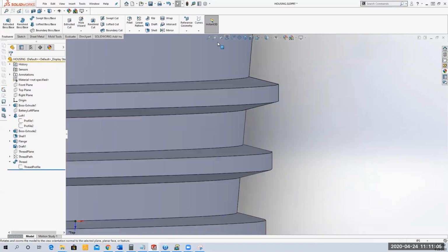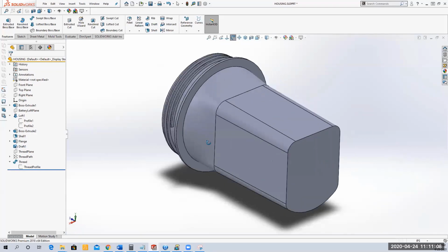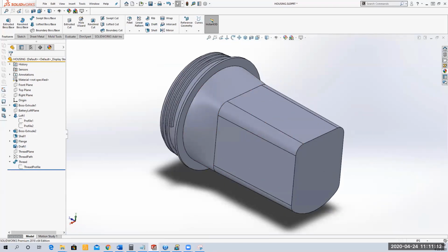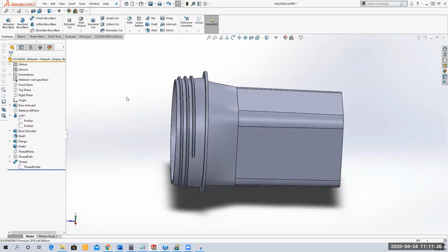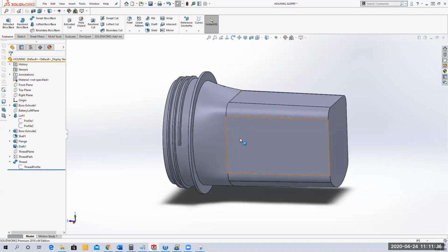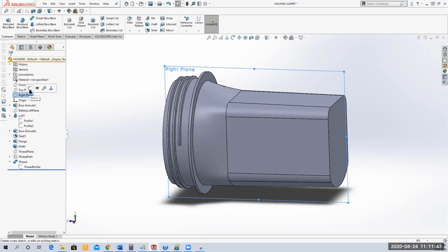Yes. Bravo. Okay, so now we are on the bottom of page 6-47. At this point, this should feel really familiar to you. It looks fairly familiar, like a flashlight that you might use when you're camping, right? What we want to do is create the handle that we are going to use when we're carrying this flashlight around in the woods. So I'm going to select the right plane for a new sketch. For the handle, we're going to use a sweep.